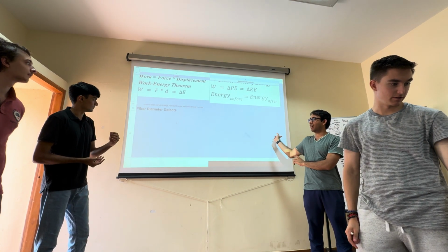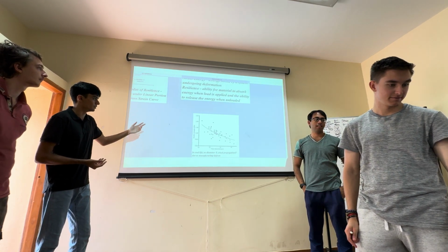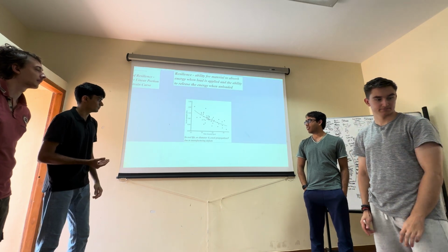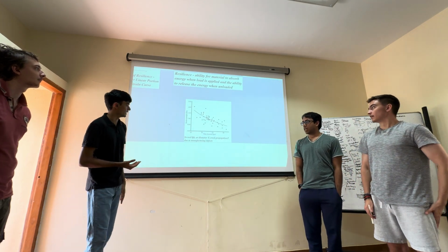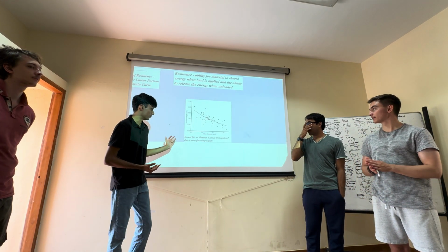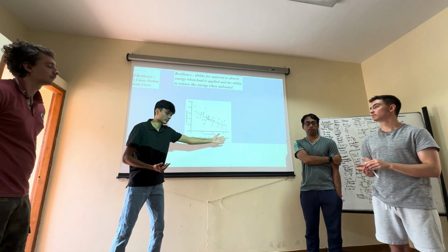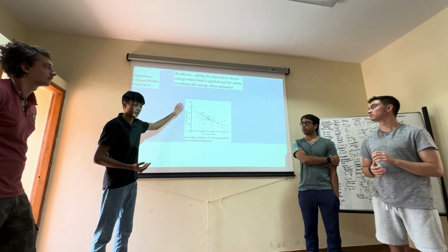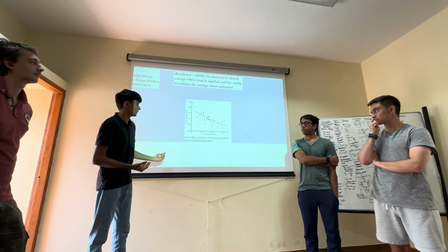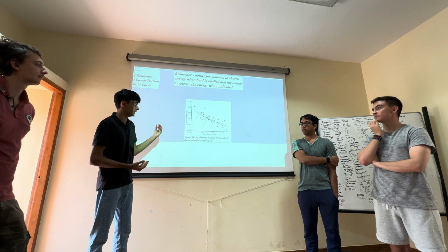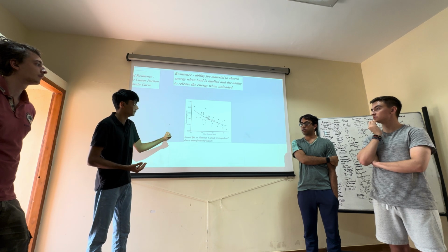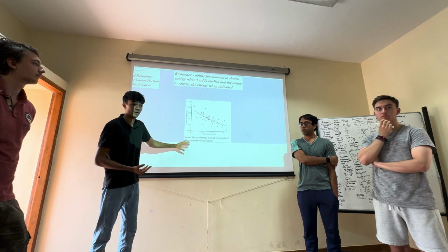Fiber diameter defects. That's different. This is something we covered extensively in class: as the fiber diameter increases, the tensile strength tends to decrease. That's not because of a specific property. It's more because of manufacturing defects.